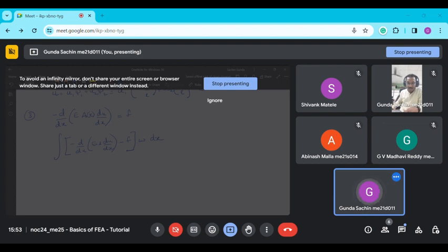And if we use this directly, we have a second order derivative on u, so we need to use at least quadratic shape functions. To avoid that, we generally go for weak formulation, that is we use the integration by parts rule and then modify the problem.